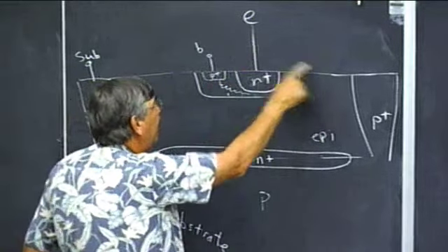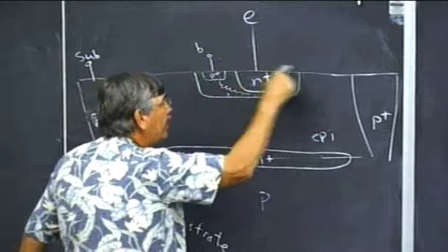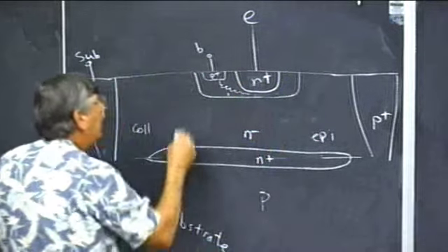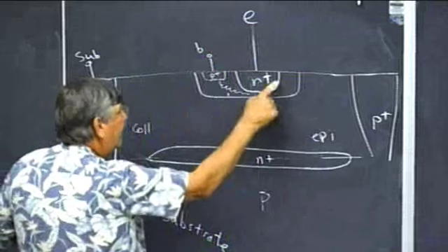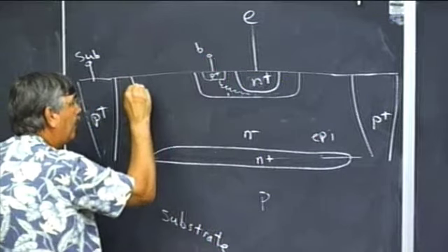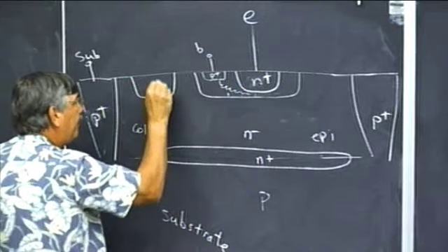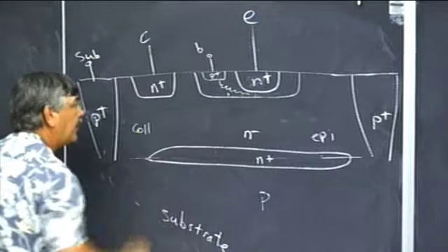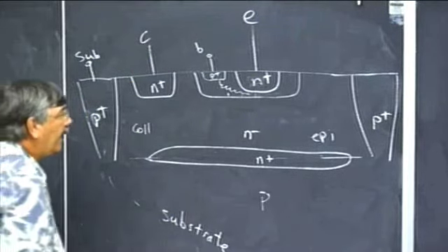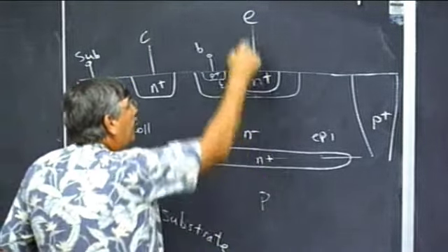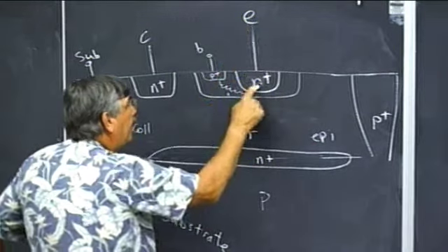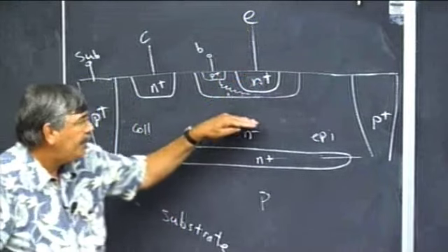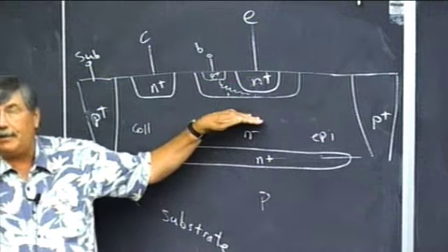We're going to grow oxide layers, and then we'll carefully put all the metal layers where they are. And we'll have an emitter, base, and I forgot to put in, when I put in the emitter, I'll also put in an N+ region so that I can make a contact for the collector. All right? This is very lightly doped. So the emitter is heavily doped, the base is moderately doped, the collector is very lightly doped.